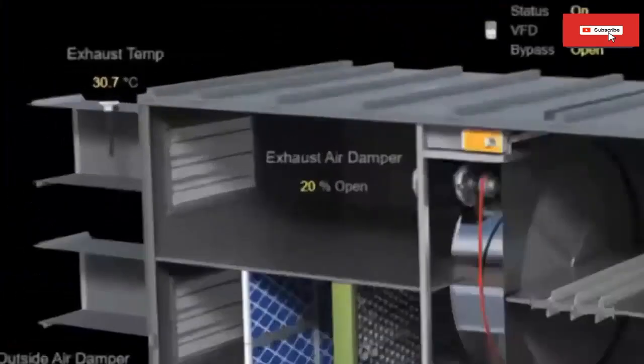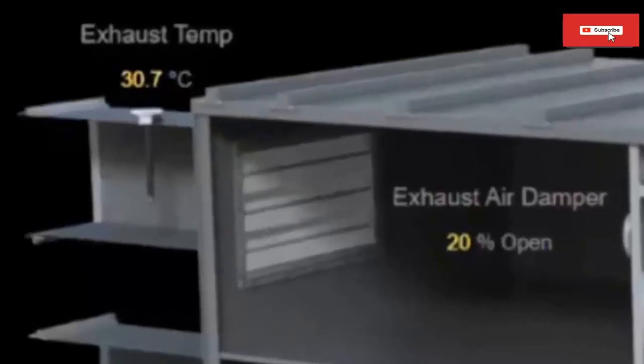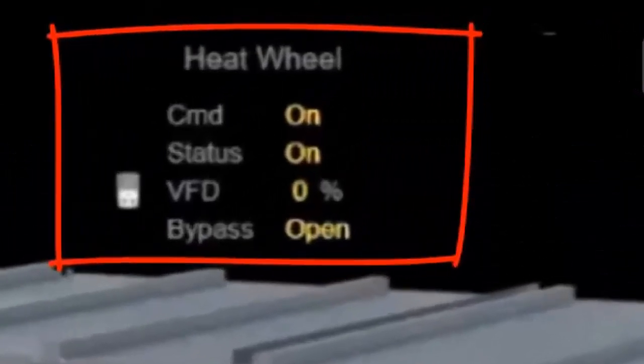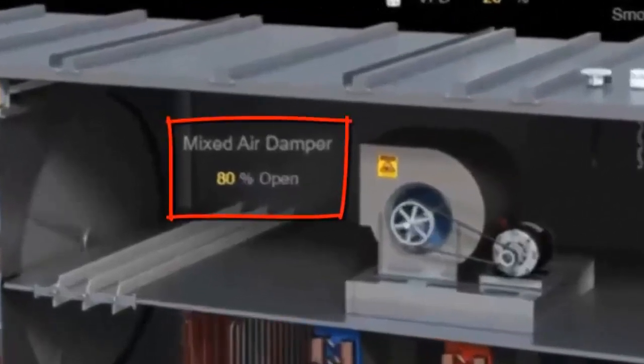10. Exhaust air temperature, the air leaving the interior to not be used again. The value recorded by the control panel is 30.6 C. 11. Air outlet door, in this case open at 20%. 12. Indicates the ignition status of the thermal wheel, in this case on. 13. Opening percentage of the damper that controls air recirculation. In this case, it is 80% open.